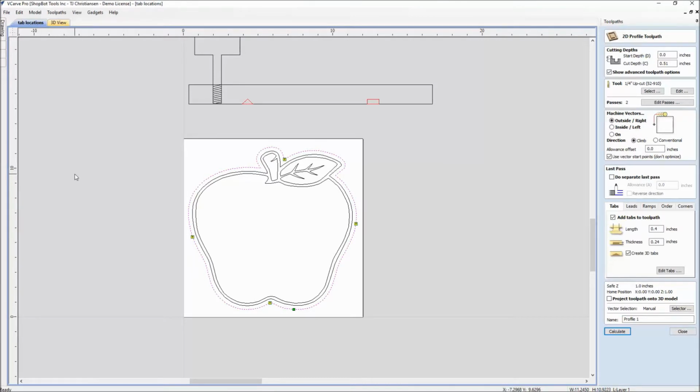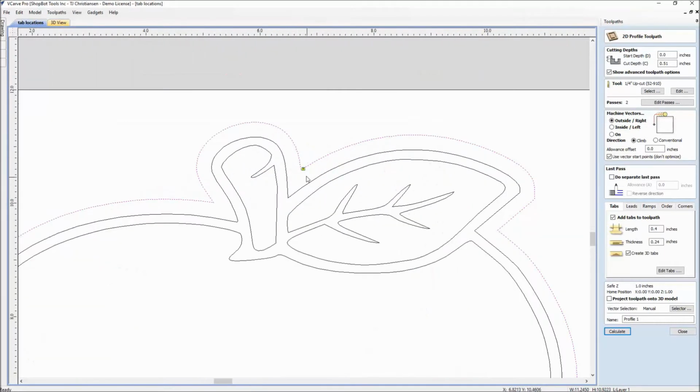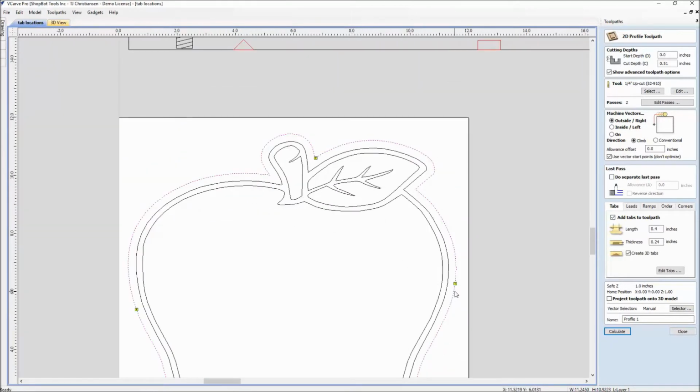We're going to look at several different things with tabs here. First of all, what are tabs? How to add them, and the locations of where to add them, which is key with the cutting. It also has to do with you cleaning up afterwards, cleaning up tabs in spots that are easier to get to. So the sizes, the locations, and the cleanups, all these we're going to look into so you get the highest quality edge finish while holding down your part.